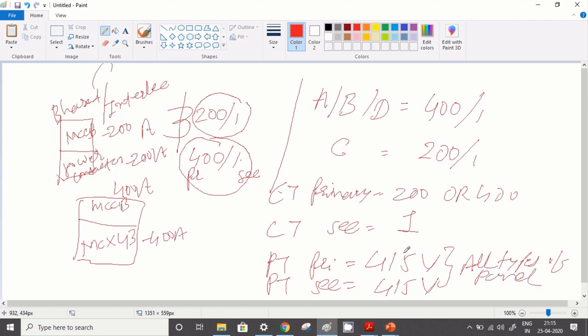So I think now you are very much clear what value we have to select for the parameters. I have told you the setting inside the SMPS for the Immersion or Vertiv and G. Immersion is very simple. In G you have to select mode 7 for the grid and mode 8 for the DG set. Once you complete your setting in the SMPS, you have to come to the LT panel in which your energy meter is, enter your password, and select your slave ID, your baud rate, and then your PT primary and your PT secondary.